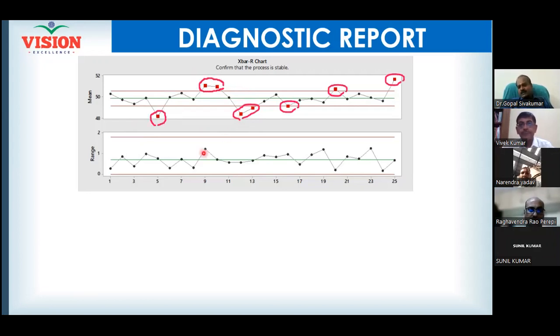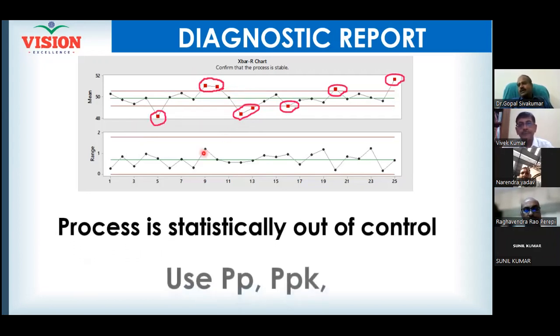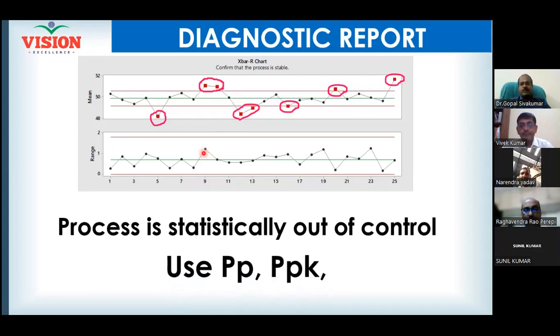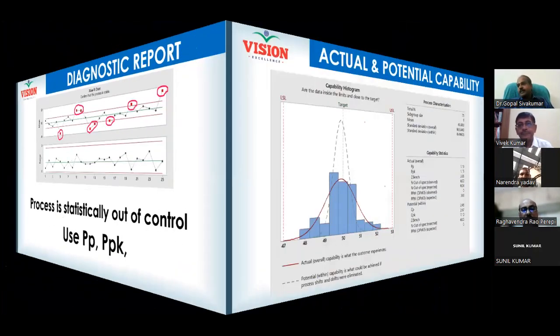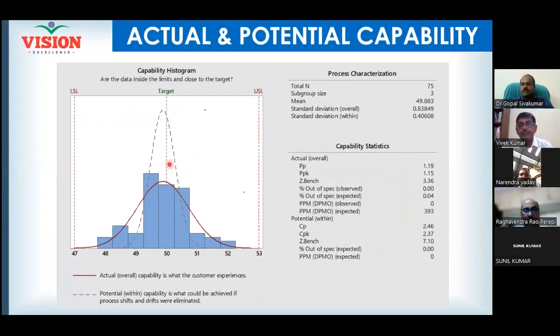But if at all the situation demands, yes, you need to do some study. At least look at Ppk. Don't look at Cpk, because that will give you a completely wrong picture. So please don't look at Cpk. So the process with the Cpk looks like this. With the Ppk it can look in this manner. Right? What is going to happen in the near future?